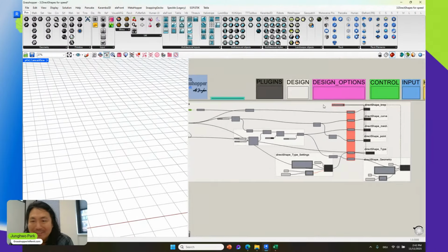And you may ask why you do that. Anyway, you can just import a Rhino file, or you can just do it by importing. But the beauty of this, when I see here, I put just a dimension as one of the examples. The dimension lines will remember the edge ID of the direct shape. So if I change this back to 30 meter,